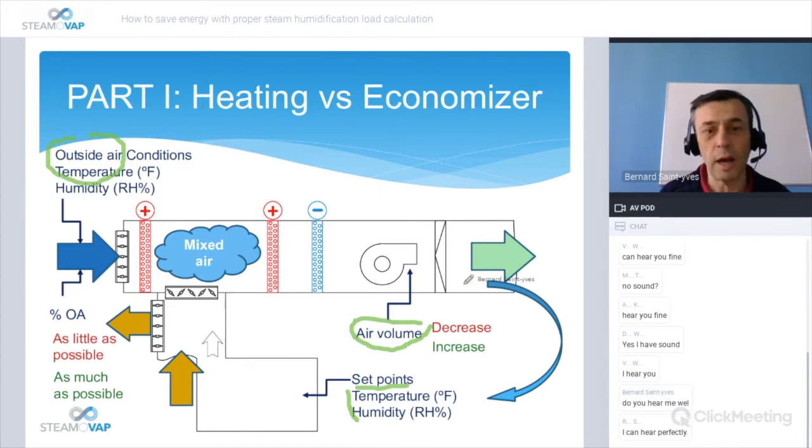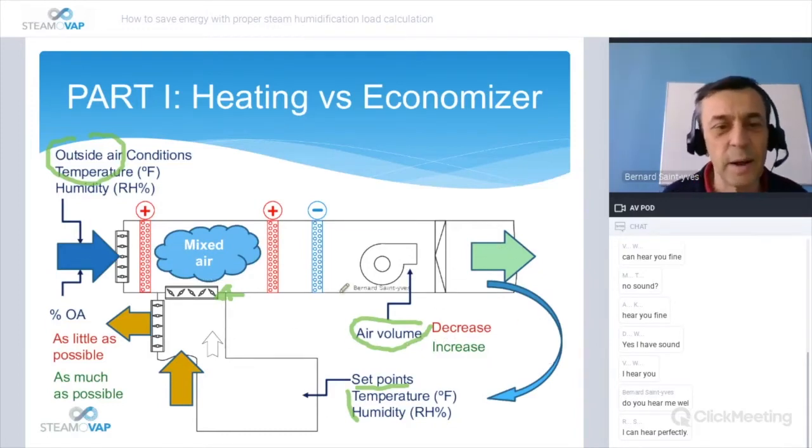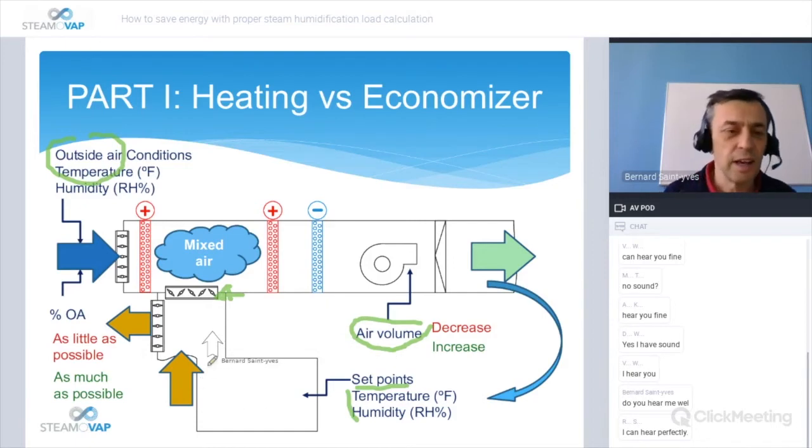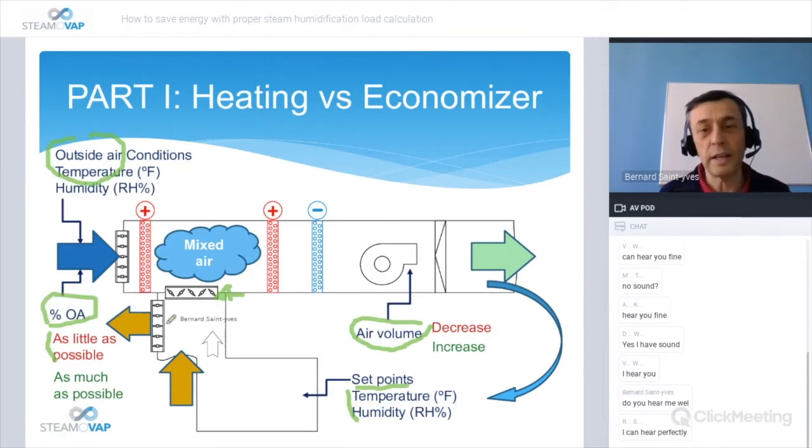And as I said, what is the application? This is a typical air handling unit. You have the fresh air, outside air, mixed air, the return, and then you can play with this one, and you can then bring some more fresh air or more return air, and then you have reheat, cooling, the fan, filters. You can have more filters, you can have the cooling and heating placed differently, but basically it's the different elements that you have. So for heating, the percentage or the quantity of outside air you will bring should be the minimum. This is obvious.